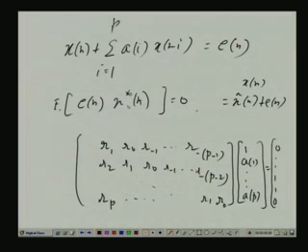If you put that back here, E n is orthogonal to x cap n, because x cap n consists of the past p samples x n minus 1 up to x n minus p, and E n is orthogonal to them. So, E n times the conjugate of x cap n becomes 0 because they are orthogonal, therefore uncorrelated. So, what you are left with is E of E n into E star n, that is E of mod E n square, which is the variance of E n.